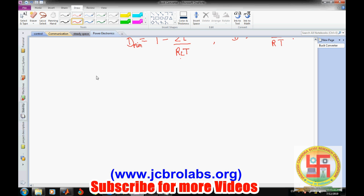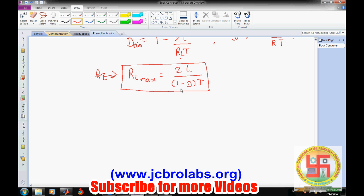Suppose we have a specified value of L. Then this RL should not be greater than the maximum value decided by RL max equals twice L divided by (1 minus D) into T. That means we can put a limitation on the load resistance for a specific value of L.